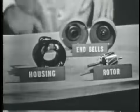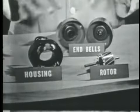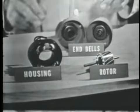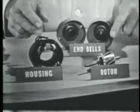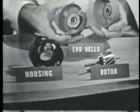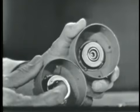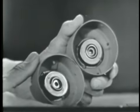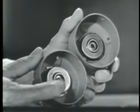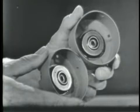Bob? Okay. This is a typical induction motor disassembled. Now, as we've said, it's very, very simple. We have the 2 end bells, the stator field windings, and the rotor. Now, let's take a look at these end bells. The end bells are used to house the bearings or the mounting devices that hold the rotor shaft in place. Now, notice there are no brushes or complicated brush holding devices at all. Just simply hold the bearings.